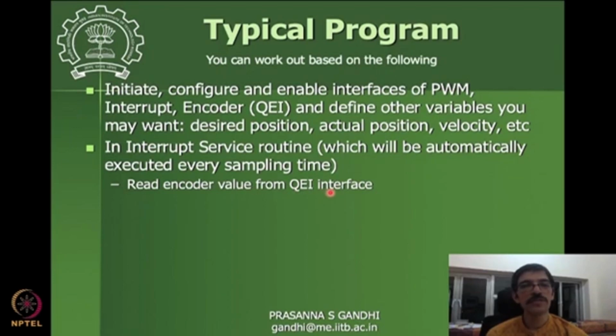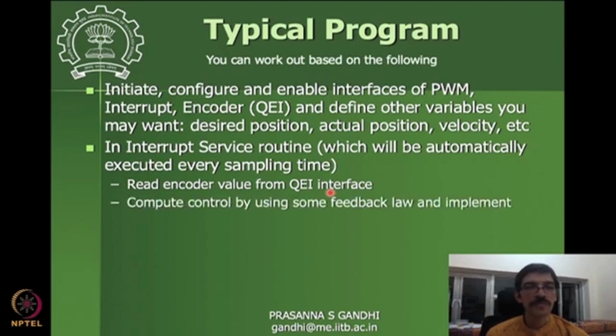All other things are going to be constant for this particular program. Only these changing parts, which are changing every interrupt cycle, should come. Now you have to compute control by using the feedback law. We have seen some law, proportional law or something like that, and implement it.